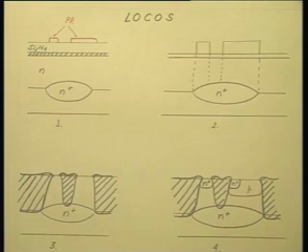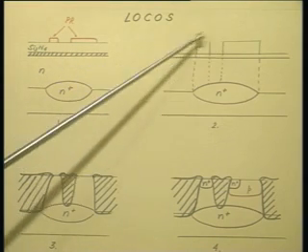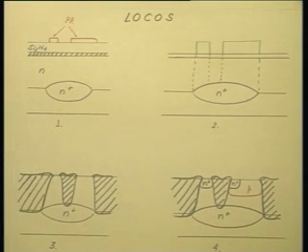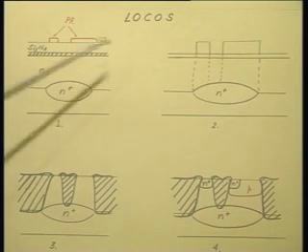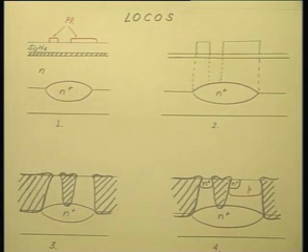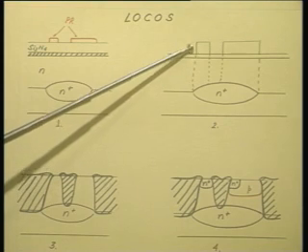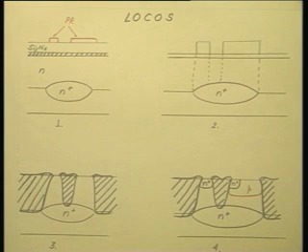That means 550 angstrom is on top of the erstwhile surface, while 450 angstrom is below. Okay. So, if I simply use this silicon nitride as the mask and subject it to oxidation, then in the regions where oxidation proceeds, I will have silicon dioxide coming on top of the surface. Again there will be loss of planarity. Do you understand the problem?